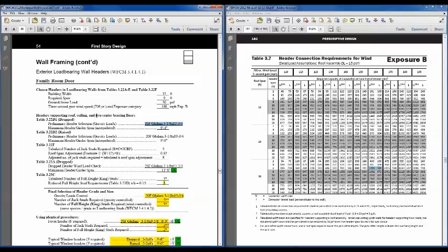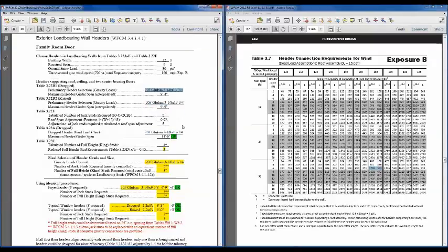One thing about the assumption for 2 center-bearing floors is if all of your windows line up from second floor down through the first floor, then you've already carried your floors and your roof system above. So you could possibly get by with smaller headers here, but you still need to make sure that you do your jack stud analysis and come up with the correct number of jack studs based on both floor systems, because that's based on bearing.